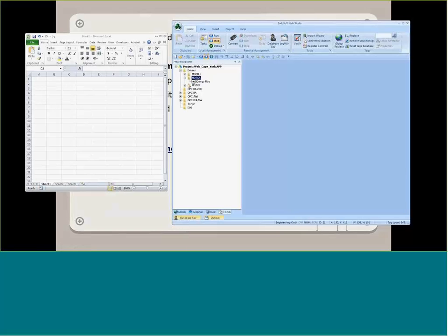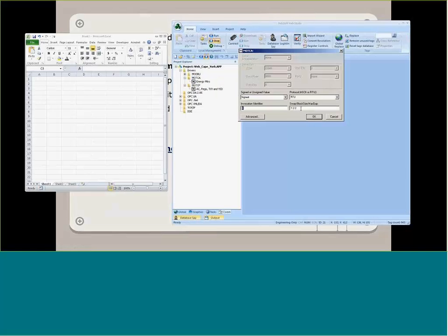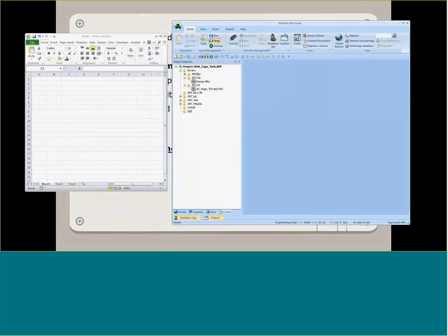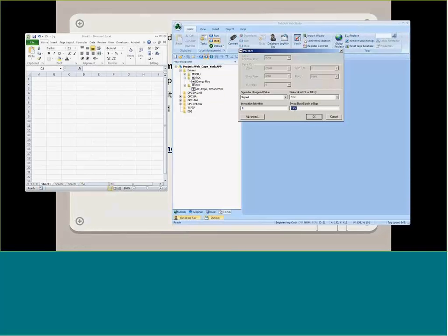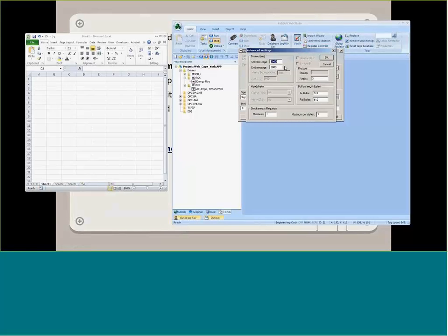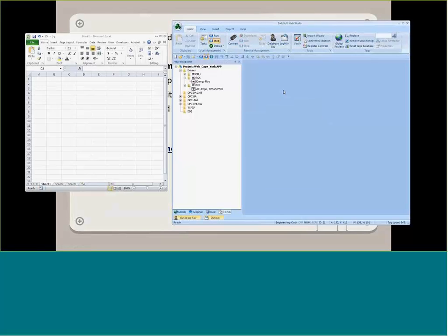What we did was the energy meters on this particular site could only handle a small max block size. So to prevent having to slow down the communications bus for everything, we actually used a different block, and we could get a few more blocks in. So when you've got a lot of serial data, sometimes I think that's a good thing. We could also have individual timeouts and retries. So we thought that worked well.